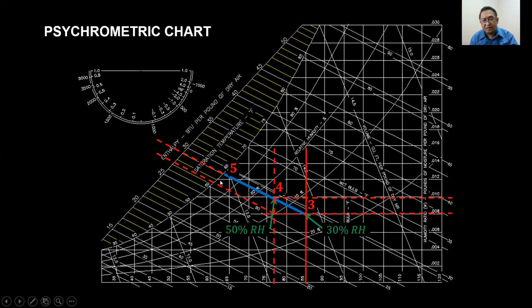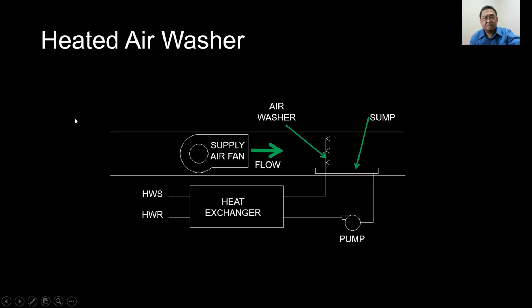And so the process will follow this constant enthalpy line, it's adiabatic here. So it will be somewhere here. Okay? And 50% humidity is your aim. So you will have a temperature between 75 and 80 Fahrenheit.